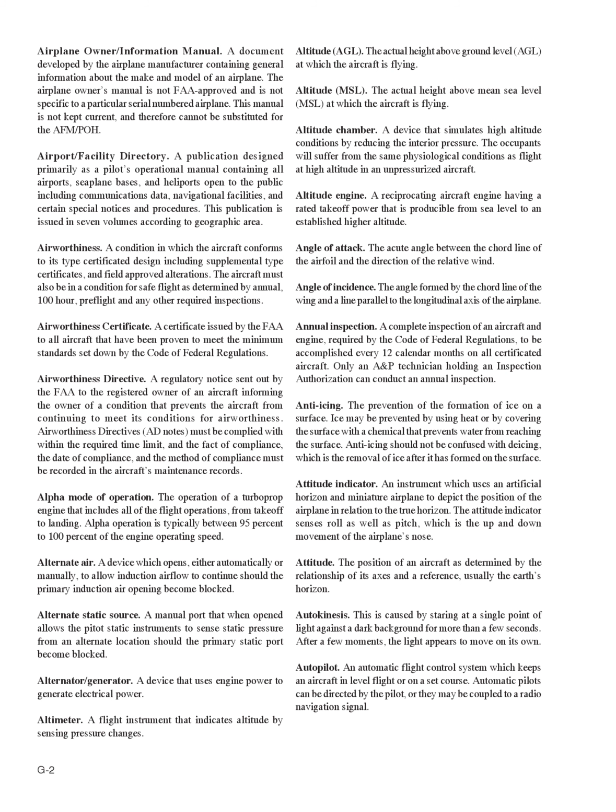Annual inspection. A complete inspection of an aircraft and engine, required by the Code of Federal Regulations, to be accomplished every 12 calendar months on all certificated aircraft. Only an A&P technician holding an inspection authorization can conduct an annual inspection.